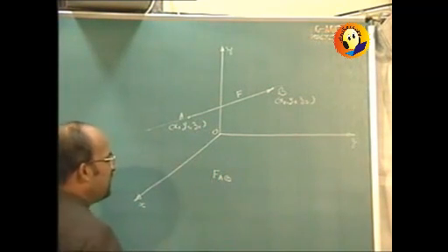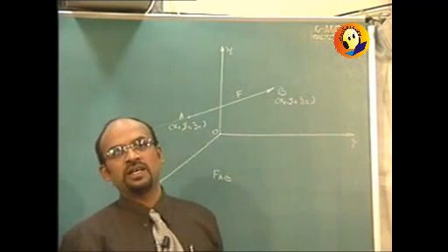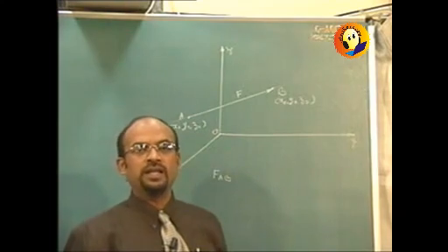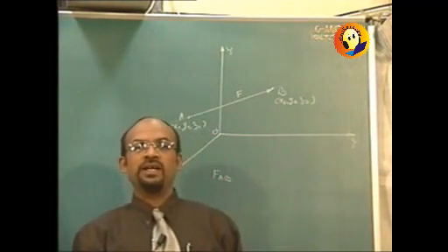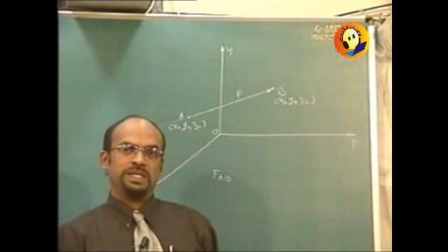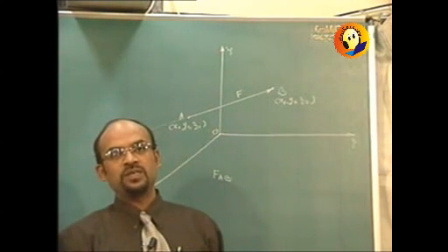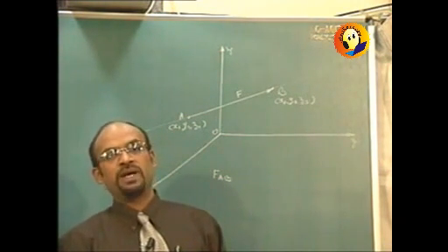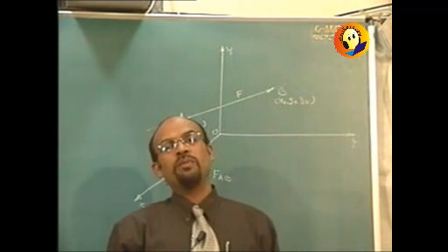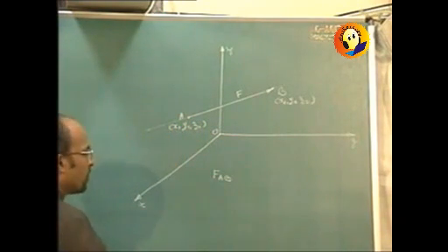Now as we have seen in 2D, the force is going to have magnitude as well as direction. Now if we are to write the direction in 3D, it is not possible to write the direction as making some angle, because which angle are we going to specify? So here we will write it as the angles with x-axis, y-axis and z-axis, respectively known as theta x, theta y and theta z, or we could write it as a vector. So let us see the vector approach for it.